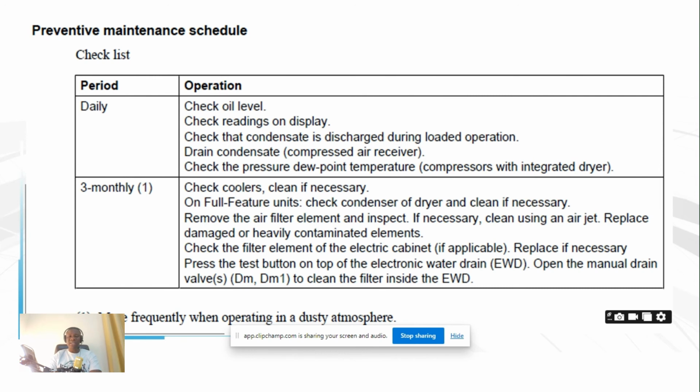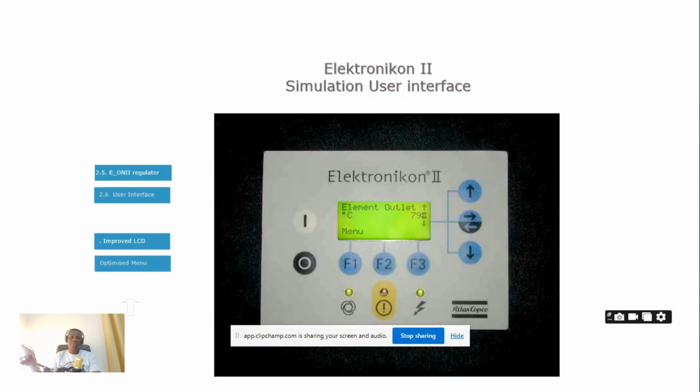Well, I didn't talk about this. I hope I find time to. Someone should remind me about the electrical circuits so I can talk about the electrical system. Overload relay, there are some protections for your system. If your motor, for example, is at risk, maybe the bearing is getting bad, the overload relay can trigger and your system will shut down. There are many other controls there I would like to talk about as we progress.